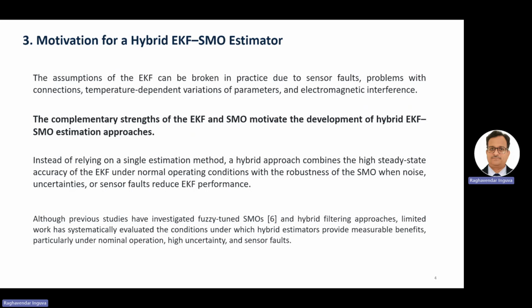The assumptions of EKF can be broken in practice due to sensor faults, problems with connections, temperature-dependent variations of the parameters, and EMI, electromagnetic interference. The complementary strengths of EKF and SMO motivate the development of this hybrid EKF SMO estimation process.